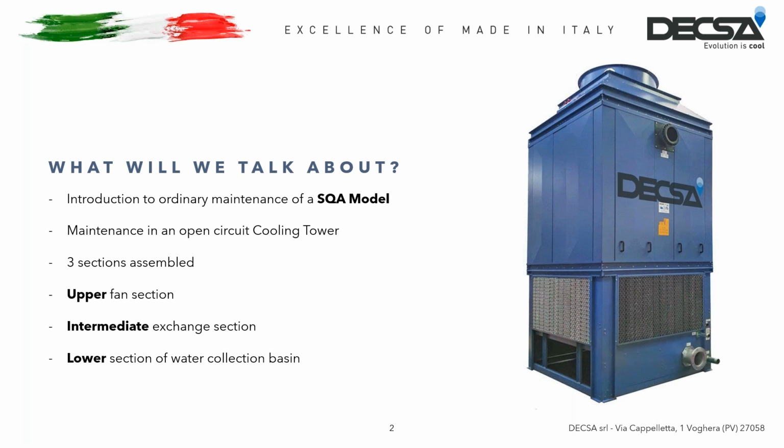It's an open circuit cooling tower designed especially for all industrial applications with water partially contaminated by suspended solids, with axial fans made of Z725 galvanized steel or stainless steel 304 or 316, or with the fiberglass option regarding only the panels.